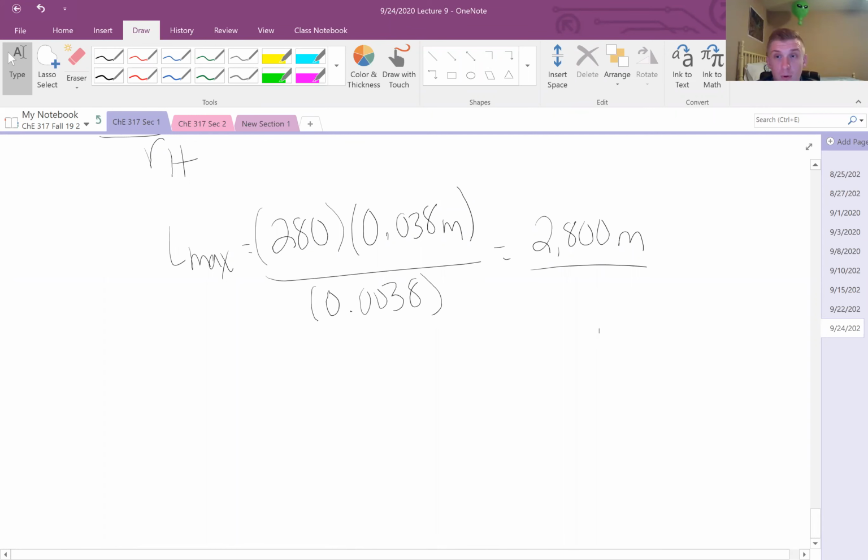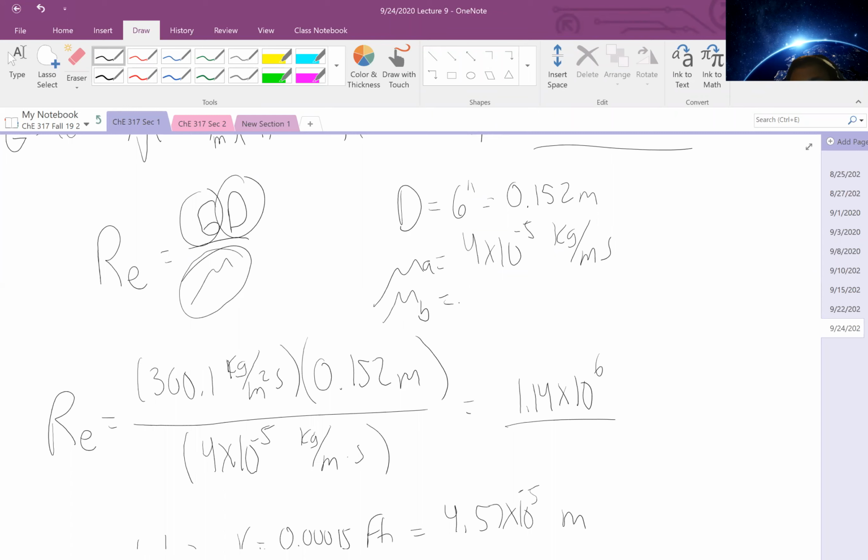So if this was an actual homework problem, you would have to consider the viscosity of both A and B. Solve for your two different Reynolds numbers based on the difference in flow viscosities. So you'd basically have to solve for essentially the asterisk condition values. You would need to know what P star is and T star is.